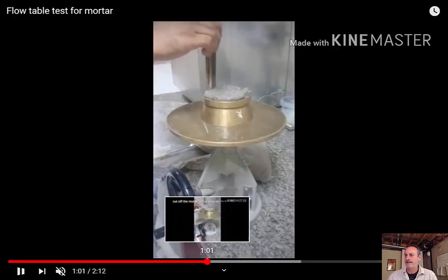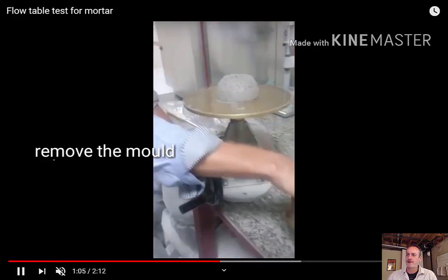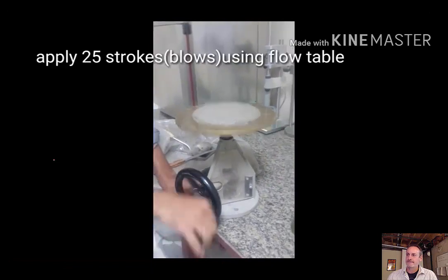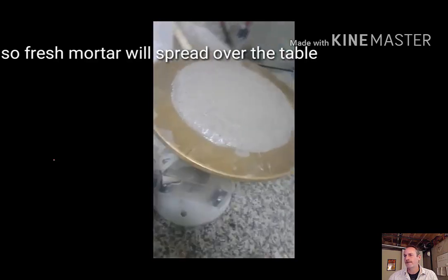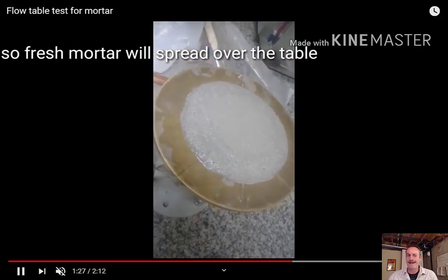After I get all of this done, I screed off the top, and then I'm going to lift it up just like the slump cone, and now turn this little lever, and it's basically causing the grout to deform out, right? So after 25 times, we see how far it's spread, and we can measure the final diameter.